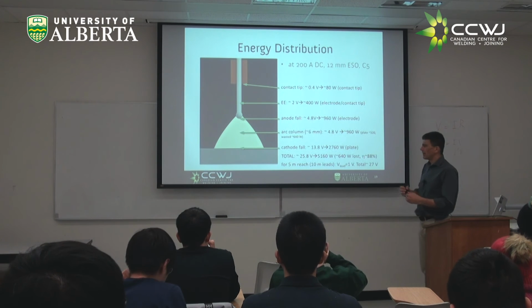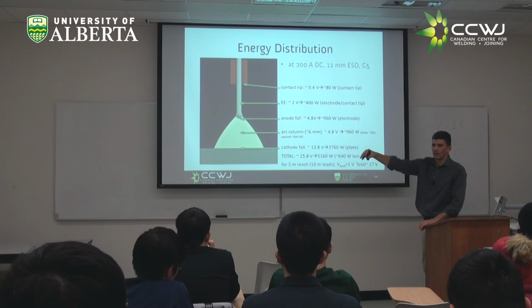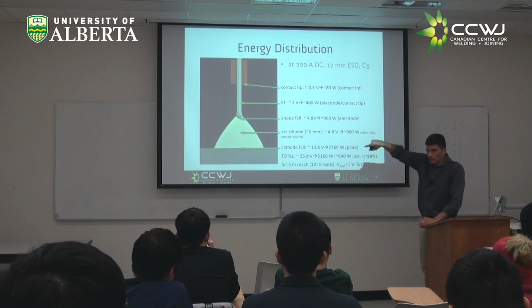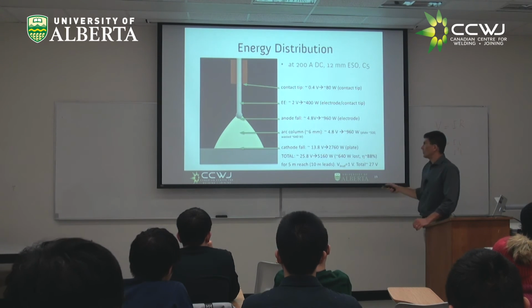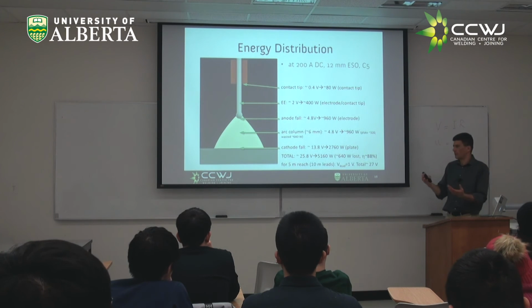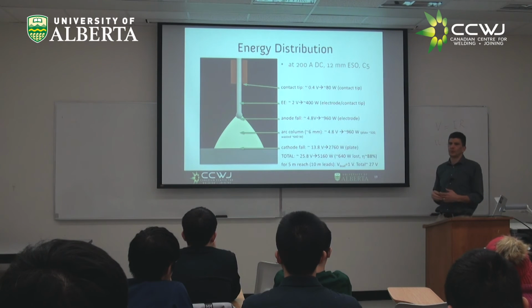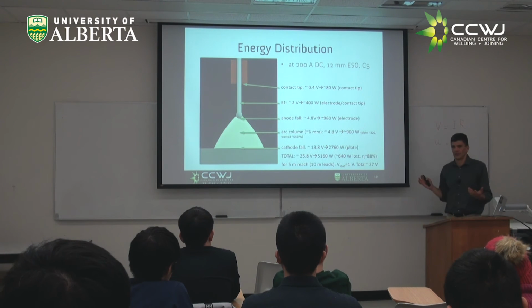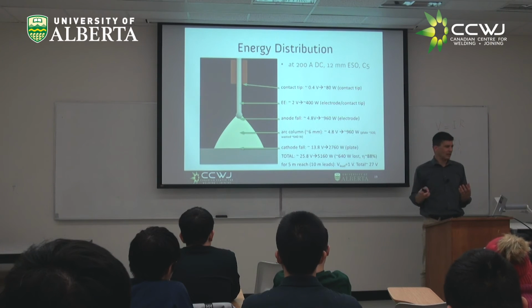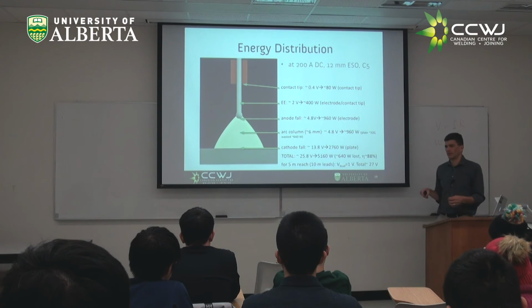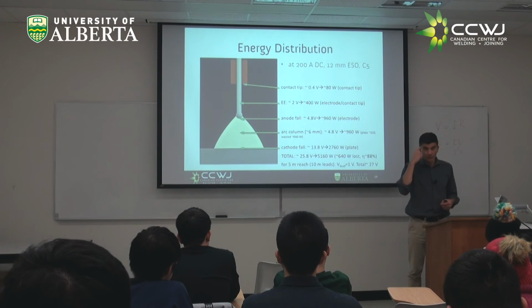Now, if we were to have a 5-meter reach for our leads, that means a 10-meter total, right? That would be 0.1 volts per meter of lead. That would be 1 volt. So in total, your machine panel would be reading 27 volts, 26.8 actually, give or take. And these are reasonable numbers. Perfect, I'm not too sure if they are perfect, but these are reasonable. In addition to being reasonable, we know so much now. We can think in ways others don't.